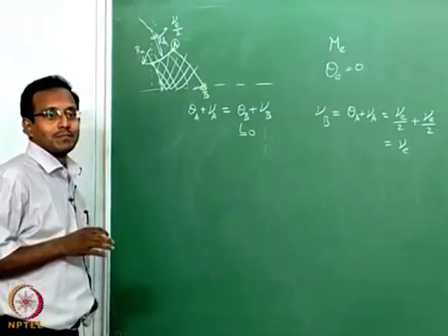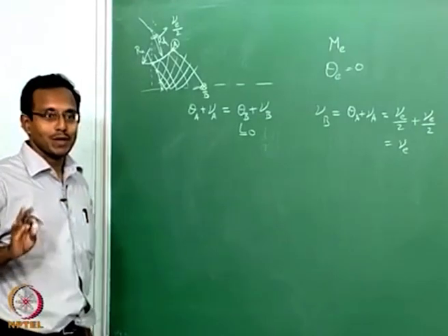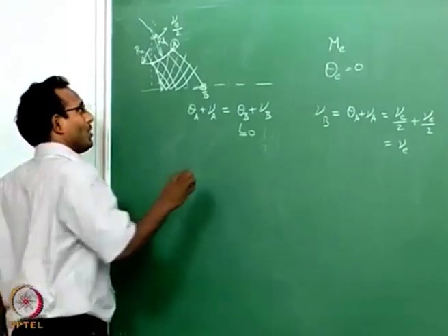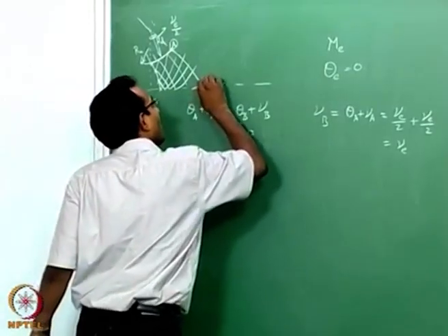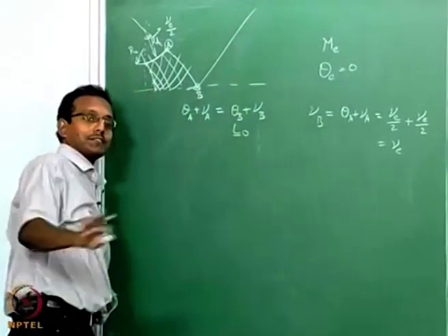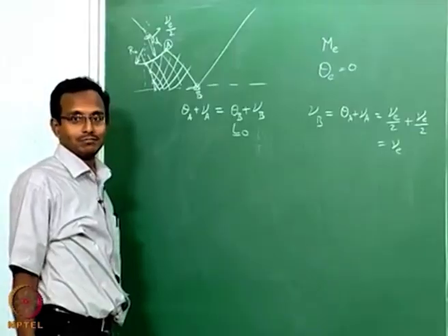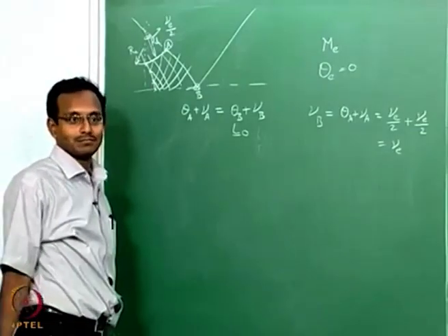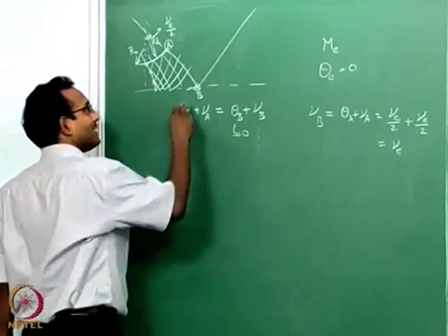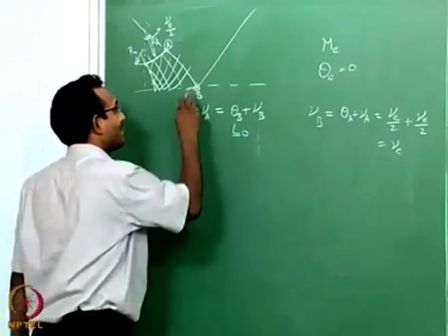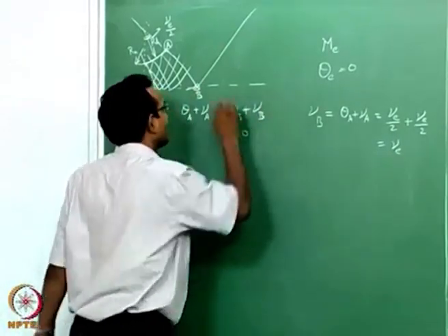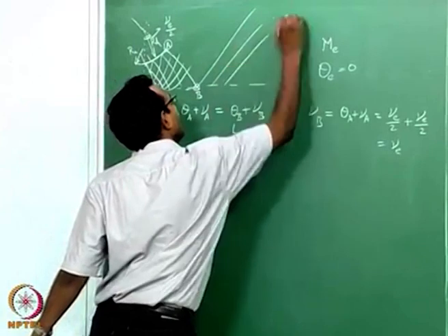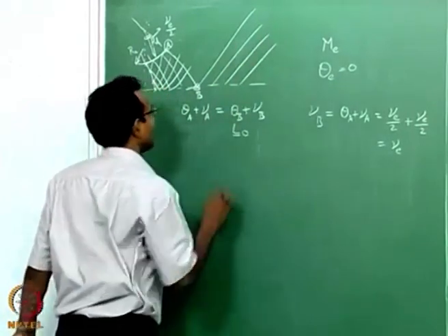Once I get that Mach number, I do not want any expansion or compression to happen. So, after this I want this characteristic to just go straight, no changes. That is what I ideally want. Once I think about that, remaining things are easy. After that, every characteristic should be parallel, then I have achieved whatever I wanted.